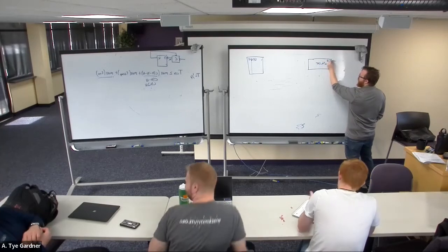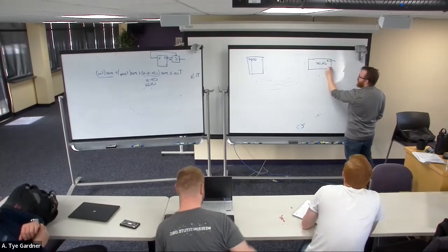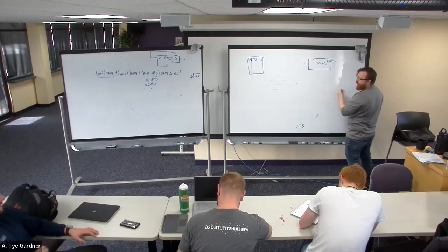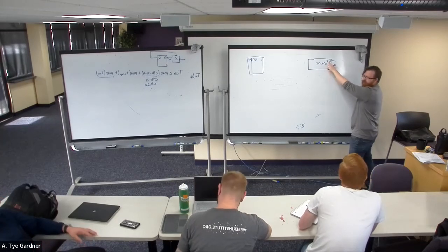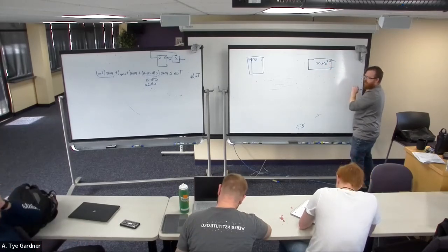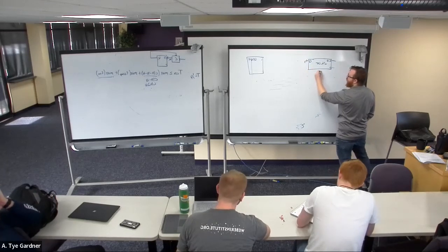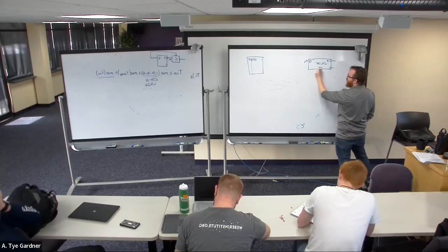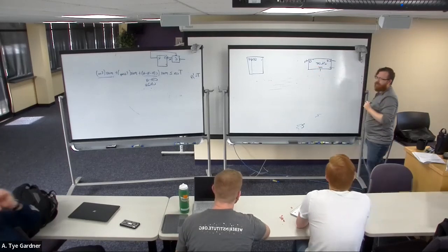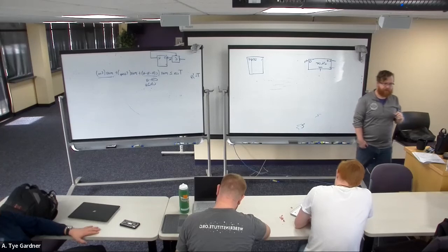This port is going to have a clock enable signal. We're going to have a clock signal, clock enabled. This turns it on. The clock. We're going to have a 3-bit Q. And we're going to have, as pointed out earlier, it might be desirable, a reset. Active high this time, no bubble. Okay.